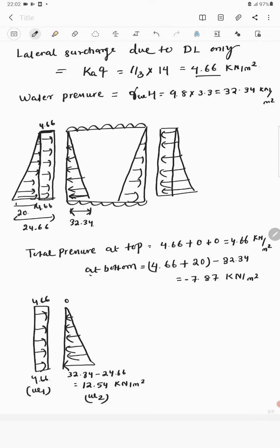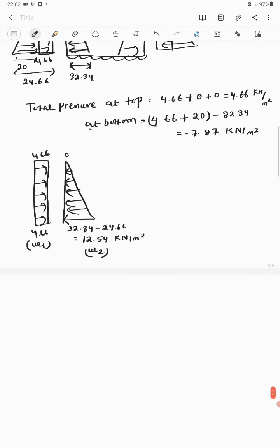Okay, now what will be the fixed end moments? MFAB is the same as previous, WL square by 12, so minus 52.5, we have already calculated in case 2. Then MFDC is the same as the previous, plus 66.11 kilonewton meter.